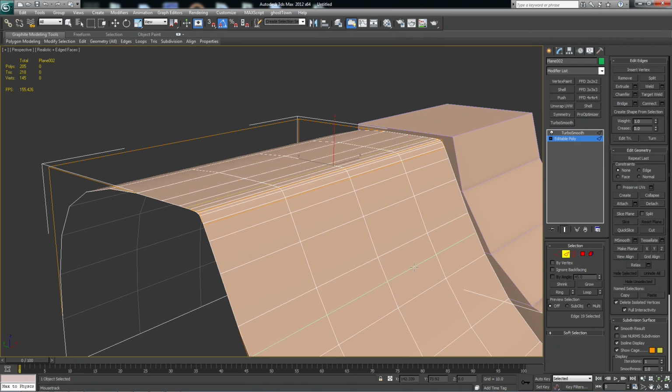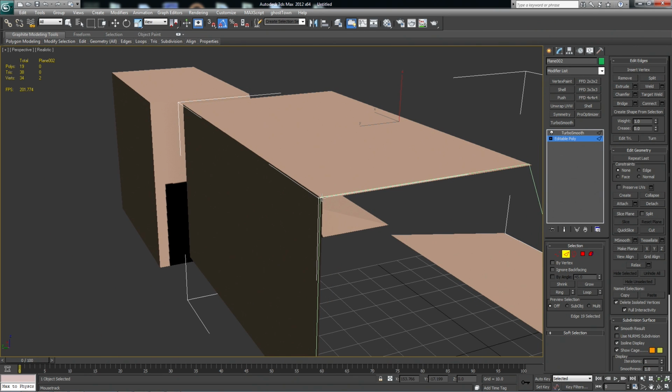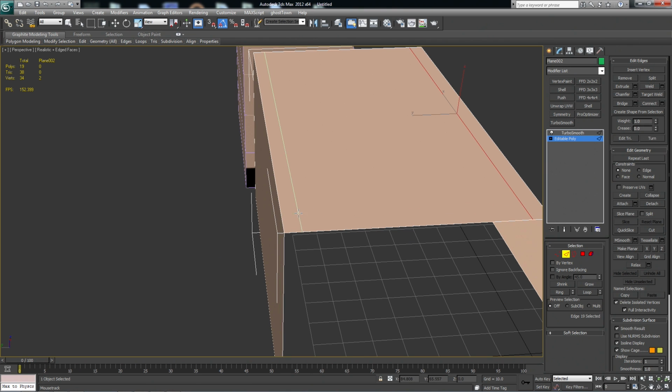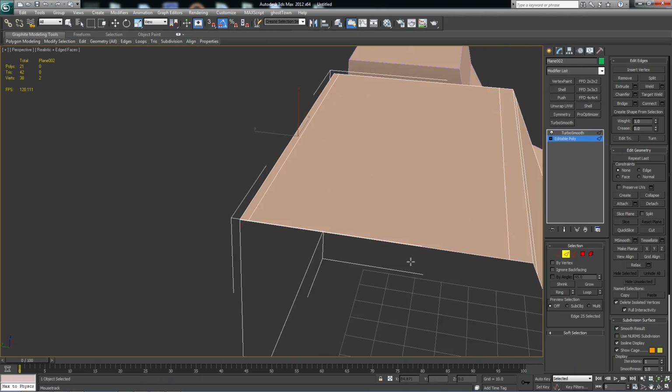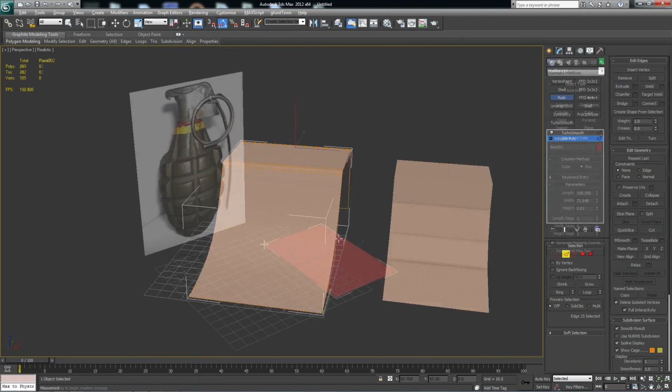This is essentially the sub-D or hard surface workflow. Create simple geometry, toggle on the smoothing to see how it looks, and then add supporting edges around the details that you'd like to maintain. Alright, let's set up some hotkeys so that we can toggle our smoothing and add Swift Loops quickly.